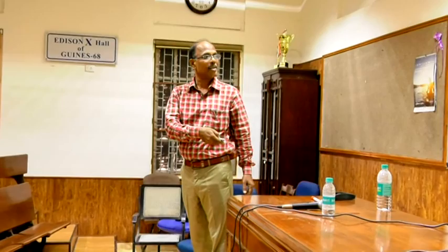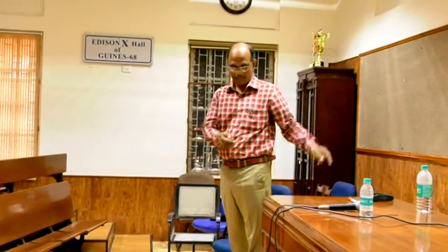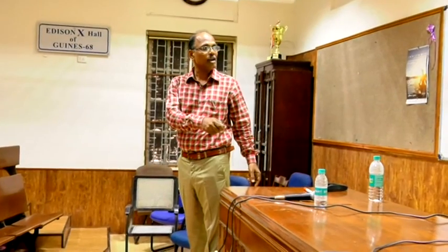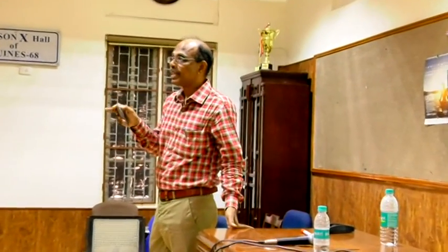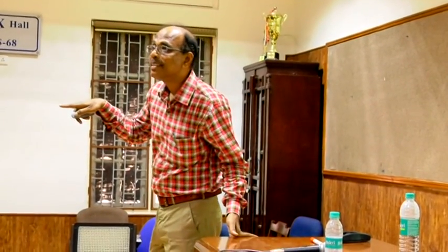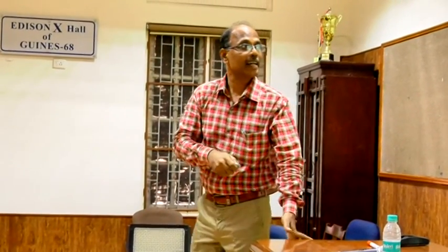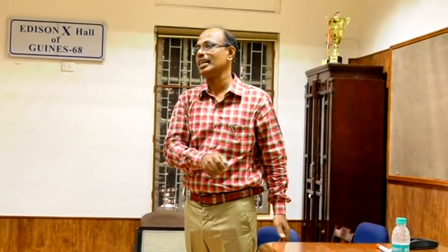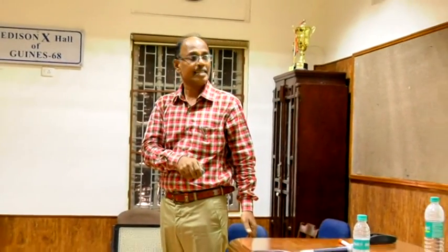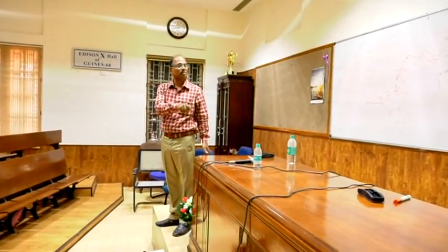Once these branch currents are formed, that can be transformed into matrix form. Here on the right hand side, J1, J2, J3, and on the left, I1, I2, I3. So the first row contains all ones. The first row must contain all ones, otherwise there is a disconnection of a line. This matrix is called the branch-node matrix C. IB is equal to C into J. J is the set of load currents, C is this matrix, IB is the branch current. So this C matrix can be formed from the network.